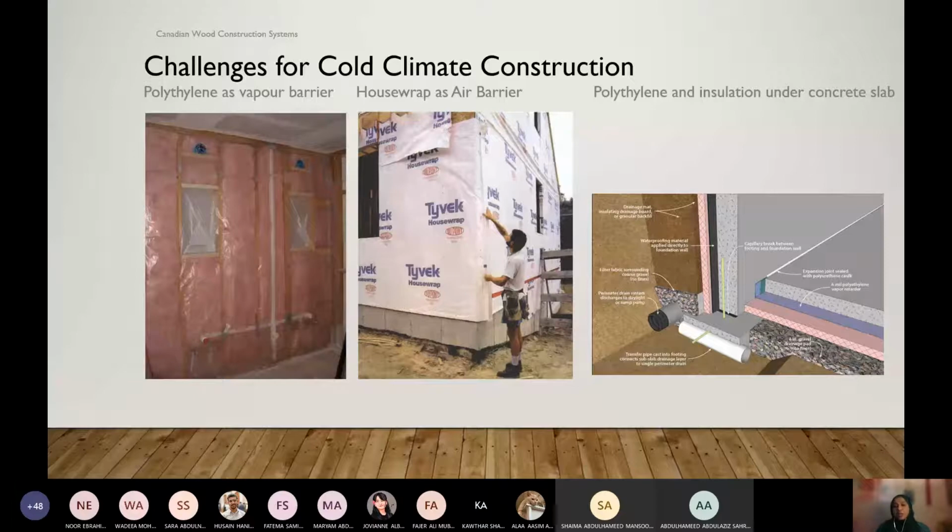Those are insulation, but sweaters alone cannot help us because it's very cold and air can pass through. So we need that jacket that acts as the air barrier. In buildings, it's the same thing. This building paper acts as the air barrier. It doesn't let any air pass through. We need to make sure of that, which is why we overlap the building papers.